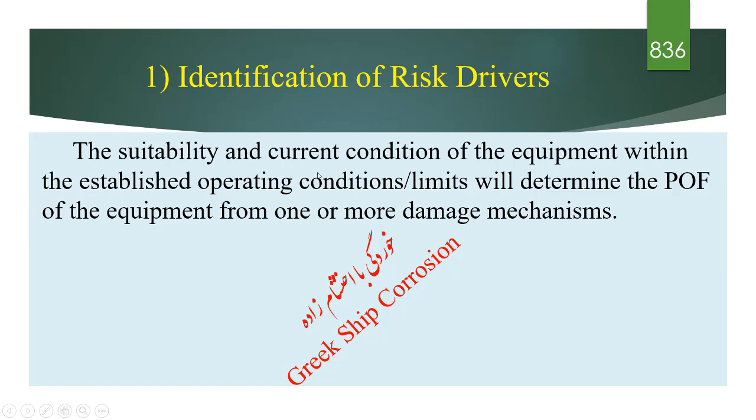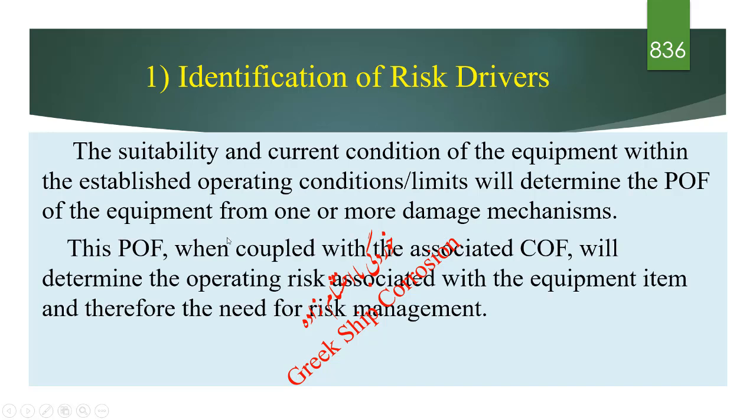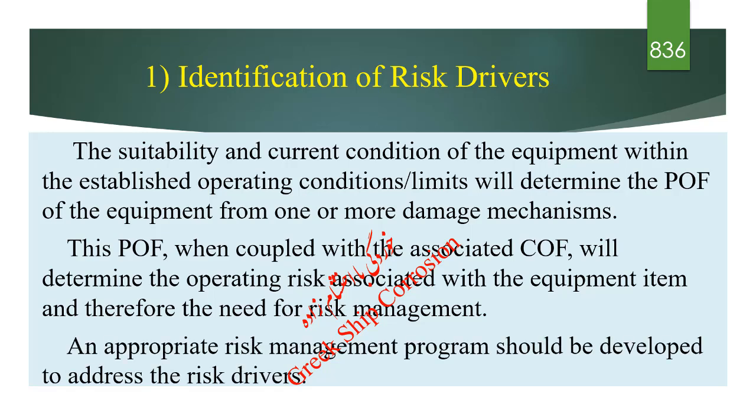The suitability and current condition of the equipment within the established operating conditions limits will determine the POF of the equipment from one or more damage mechanisms. This POF, when coupled with the associated COF, will determine the operating risk associated with the equipment item and therefore the need for risk management. An appropriate risk management program should be developed to address the risk drivers.